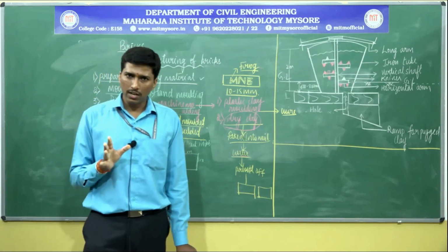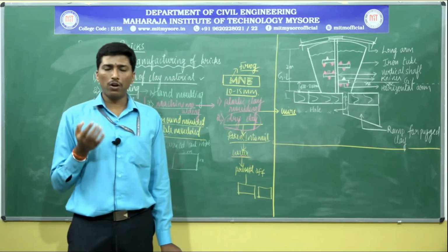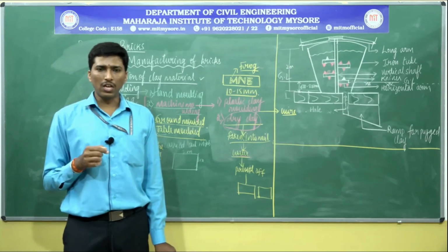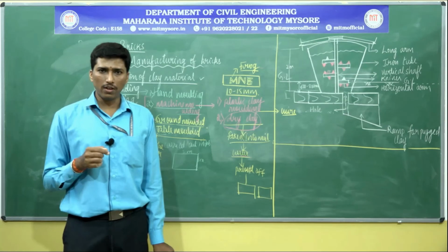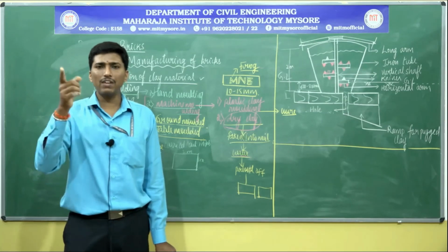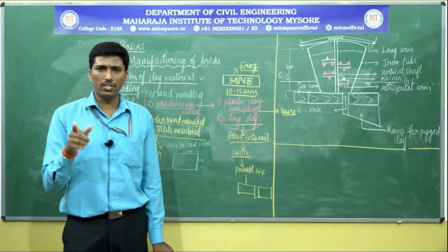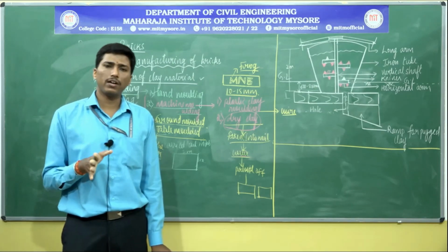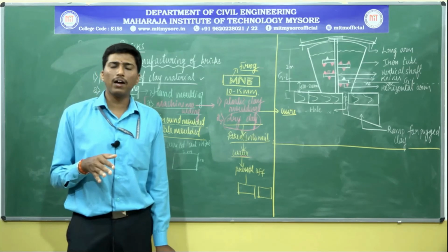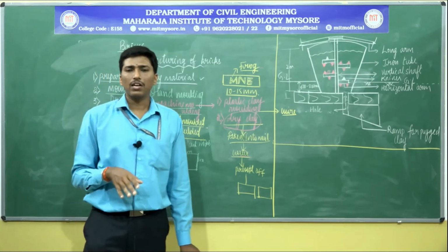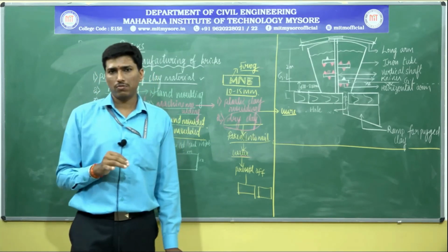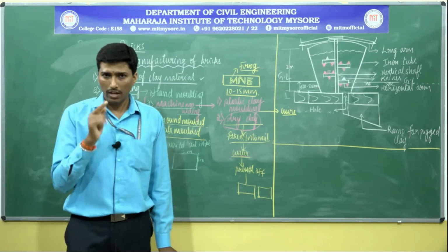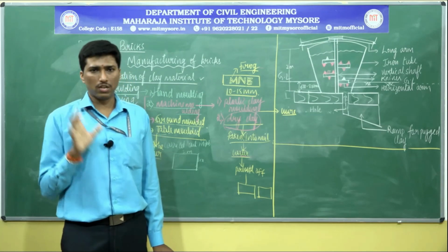These porous contents tend to deteriorate under burning conditions, which is the next stage. And you cannot utilize the molded bricks without burning directly for construction. If you use them there, the strength declines, cracks develop, or buckling tends to develop to a greater extent. Finally, they tend to collapse. The load cannot be withstood by them. Hence, care has to be taken.